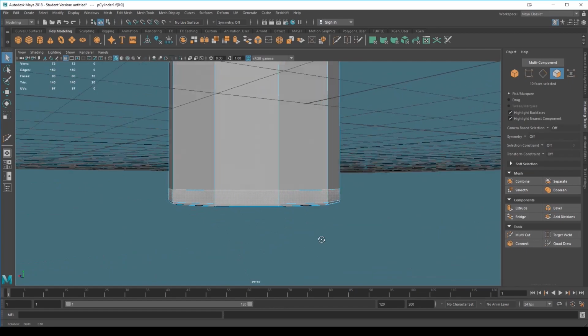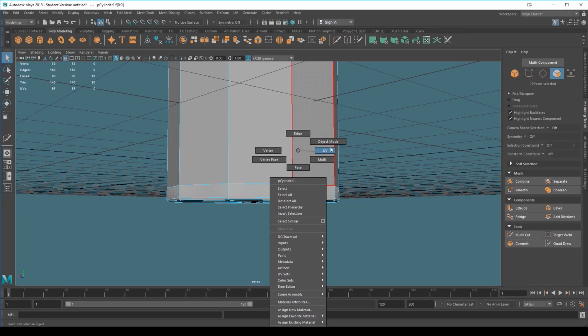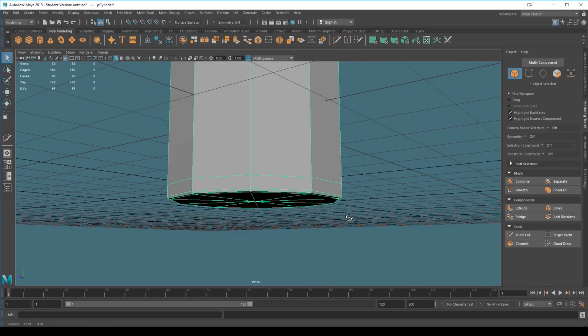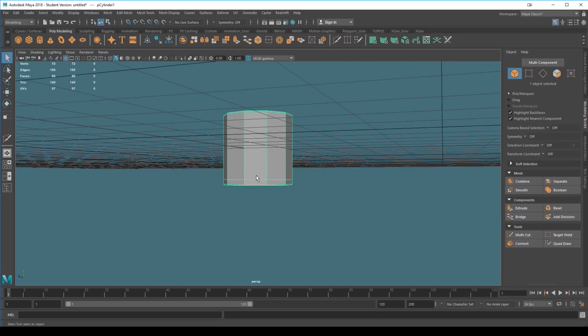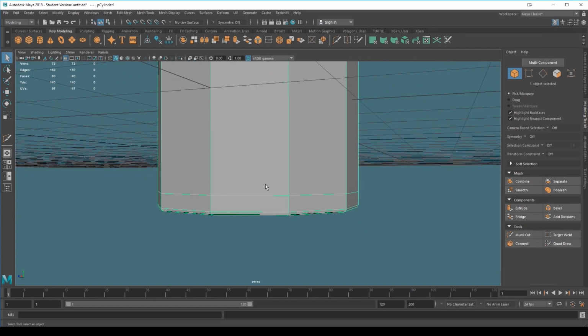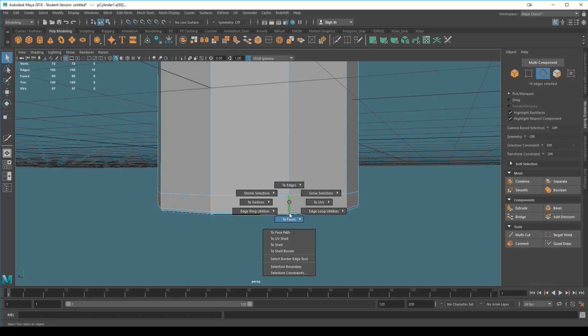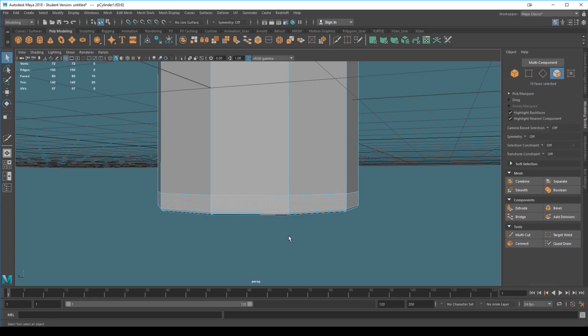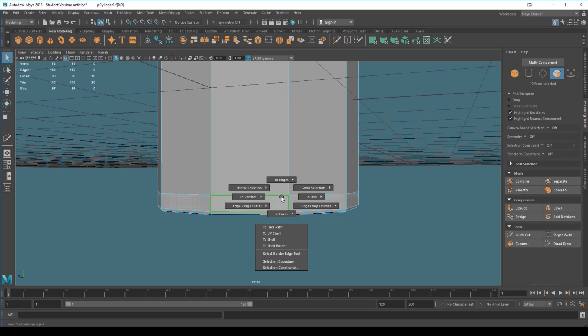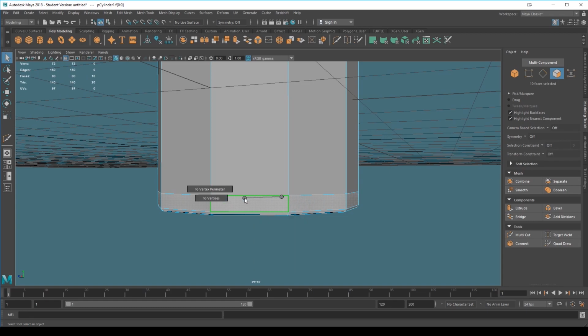Both do the same thing, but just quickly repeating that, just in case you're not in such a simple way, maybe that's in an angle and drag selecting isn't quite so easy. Just basically selecting one edge, double clicking the next one, selects the loop, hold down Control, hold down the right mouse, and go to faces. So when I hold down the Control and hold down right mouse, that lets me change the selection.